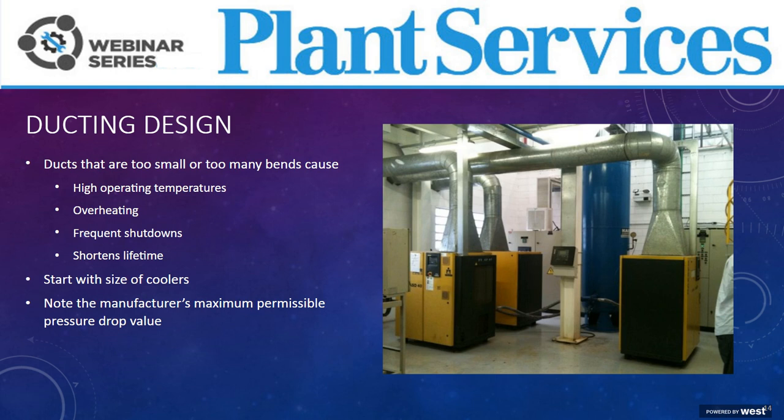Ducting is absolutely critical to having a well-operating, long-lasting system. Compressors generally have a location for cooling air discharge, and this is where the air leaves the compressor package, and this is the same for dryers as well. Without ducting, that air is going to enter the compressor room. Disregard the physical size of that exhaust location and size your duct based on the compressor's cooling airflow, the maximum permissible pressure drop, and any other pertinent information from your compressor manufacturer. The size of the opening is independent of how big the duct needs to be. In most cases, the exhaust duct will need to have a larger cross-section than this opening.